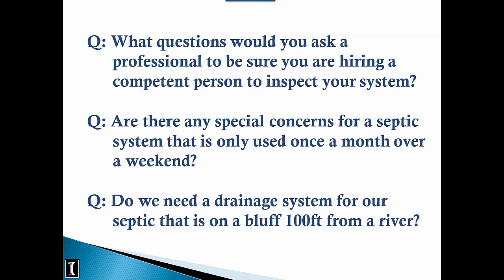Yes. A septic tank and system is really made, like we've been talking about, to have bacteria build up and come to a level that they can eat the waste that has been generated by the household. If you're only feeding the bacteria once a month, you're never going to get to that level of the bacteria count you're looking for without a constant flow, as well as the temperature of the tank increases with water coming from a residential setting. And all these will affect the bacteria and their ability to grow and come to a level to treat the wastewater correctly.